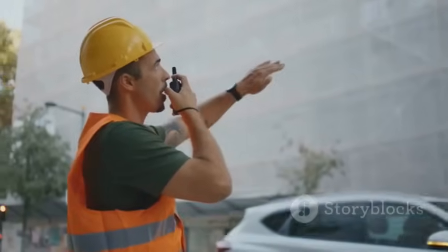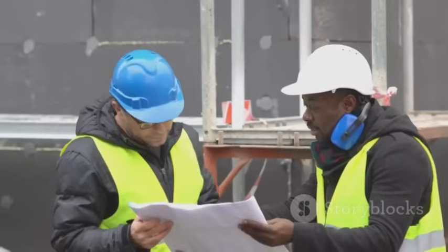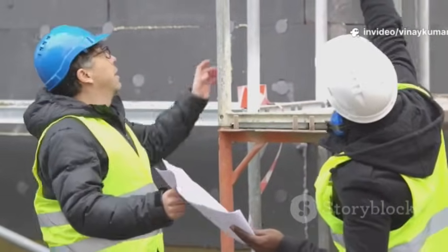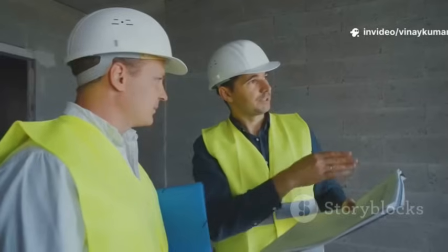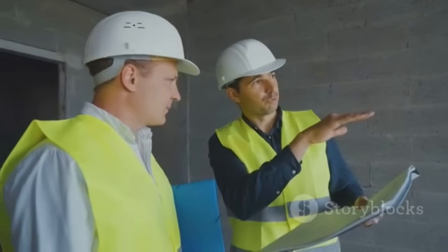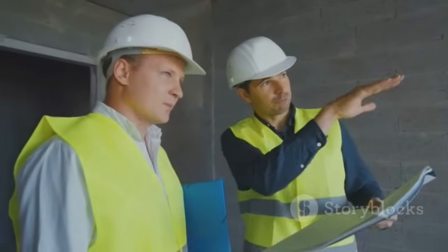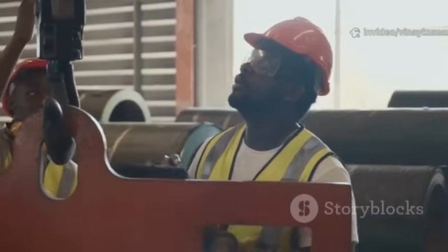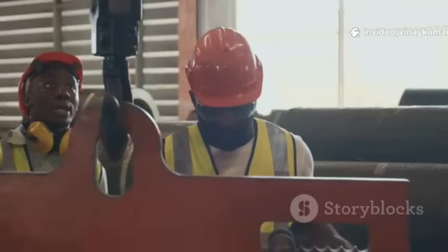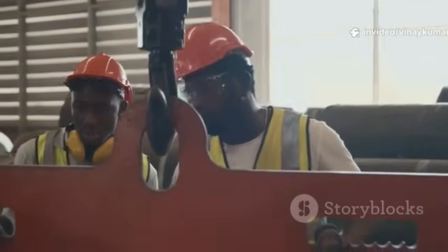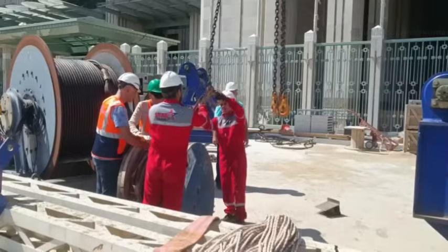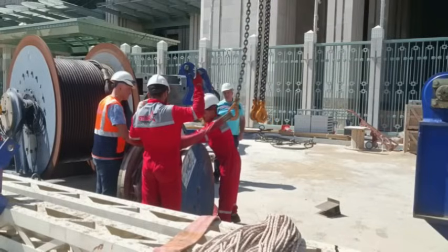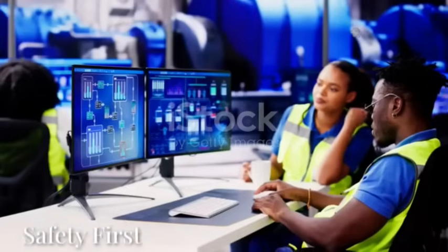The contractor in turn has responsibilities. They must ensure that their own employees are trained in the specific hazards and work practices necessary for their job. They must advise the host employer of any unique hazards presented by their own work. And crucially, they must ensure that each of their employees follows all the safety rules of the facility, including practices like hot work permits and safe work procedures. This element creates a seamless safety umbrella that covers everyone on site, regardless of whose name is on their paycheck.